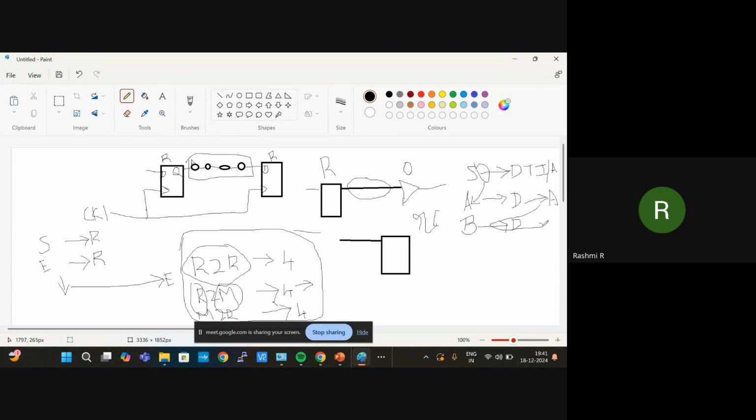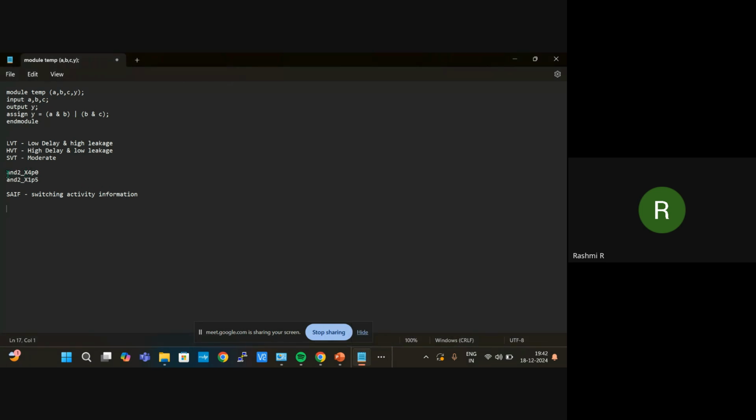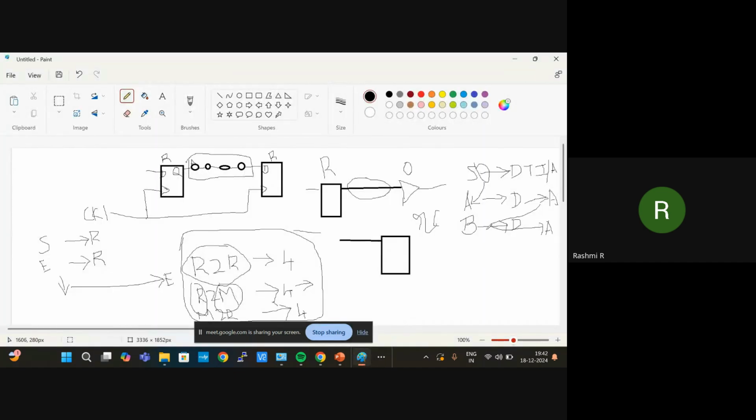Total delay will come in arrival time. In the report timing we will get the instance name and the cell name, the ref name also. Ref name, I have told you, right, will give the drive strength. So based on the drive strength and delay, we can say if the path is violating, then we can check for the cell VT class or cell drive strength.